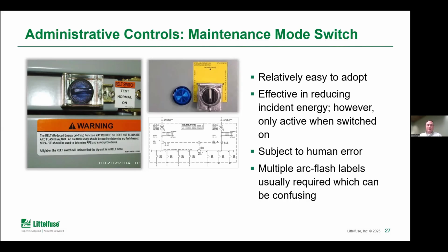Now, the issue that I've seen in some cases with this switch is that it's still subject to human error. So it relies on somebody flipping the switch into maintenance mode before they work with the panel. And it also requires somebody to remember to turn it back into operating mode after they're complete. So it is something that relies on that process or that human element.